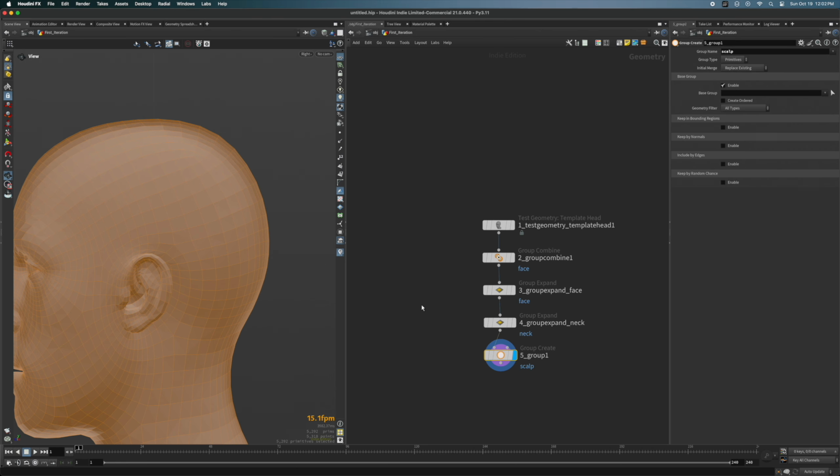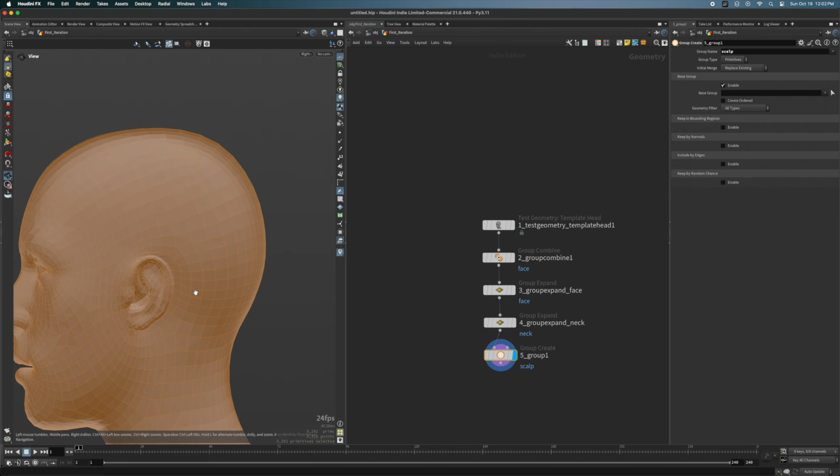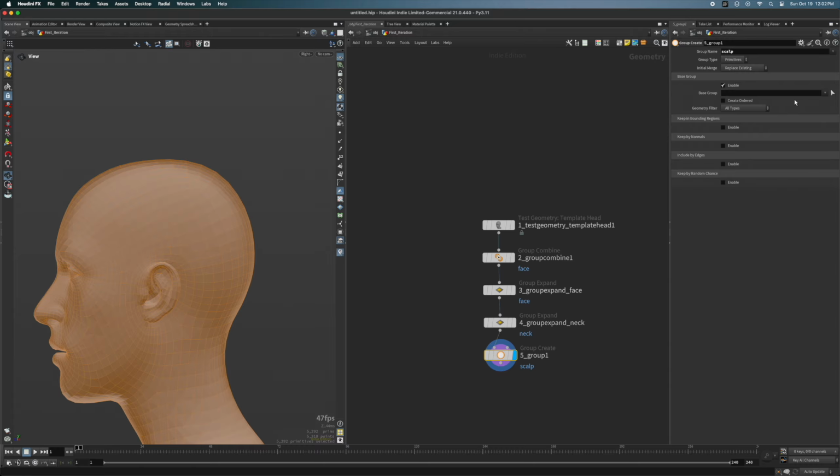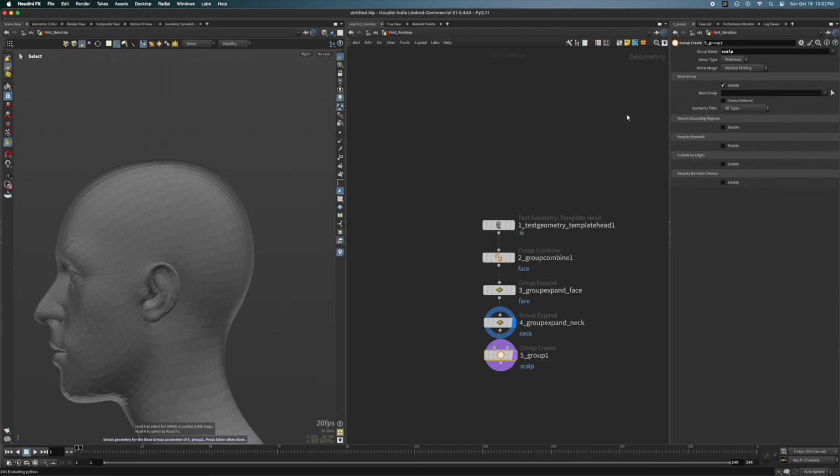Then using the selection icon in the base group, I can now enter a state where I can interactively drag out a portion of polygons that I want to keep, or primitives. I prefer to have the settings for selection on as lasso instead of box. And also, I'm going to turn off the select visible only option so that I select polygons that are on both sides of the head.